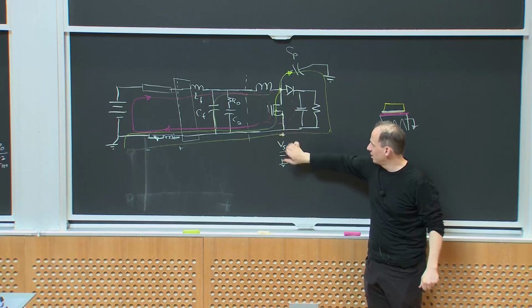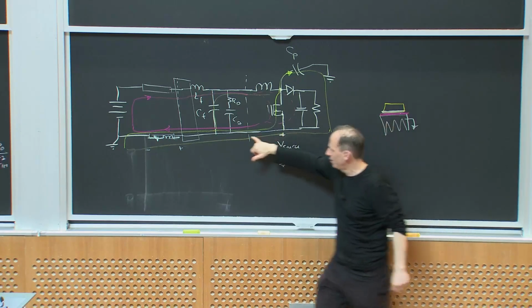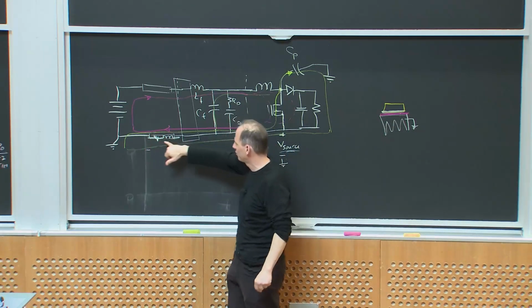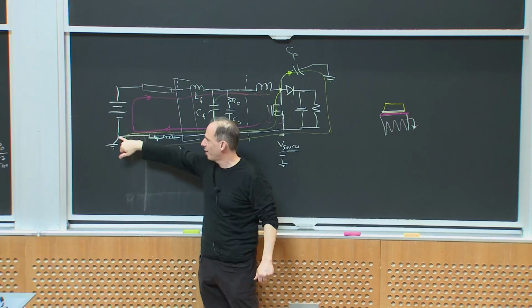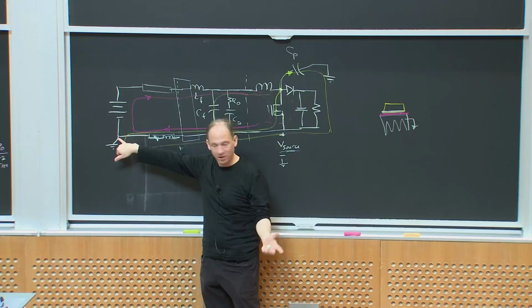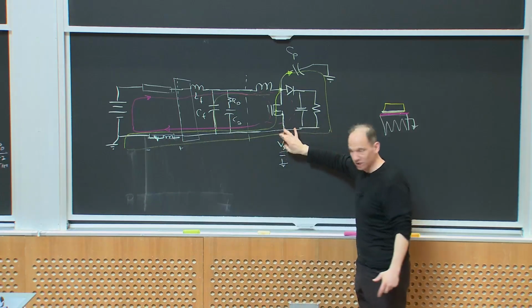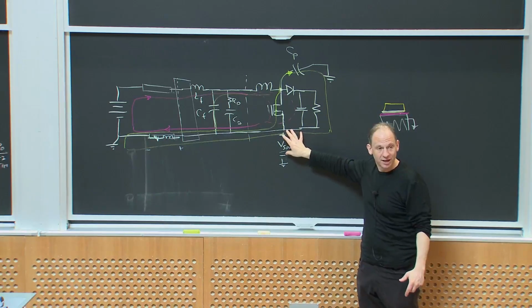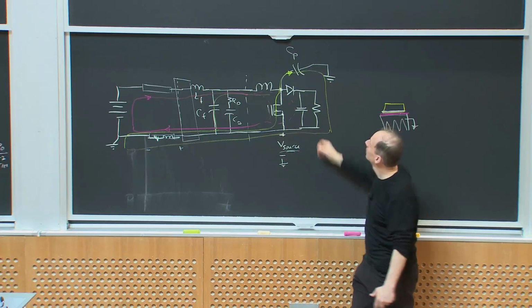So we can see, even though in an ideal world I intend this node to be a zero resistance, zero inductance wire, and I intend there to be no voltage there, because it's not an ideal wire, it's a real one, there will be ground bounce here that I have to contend with. Okay?